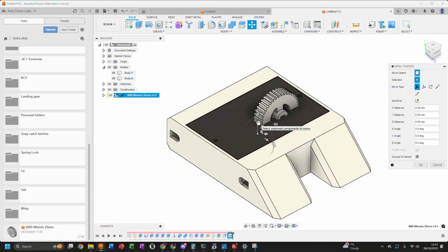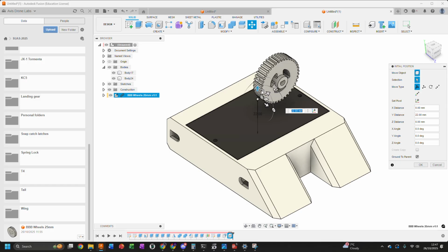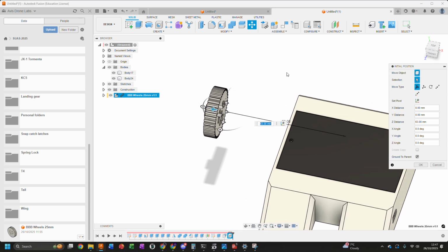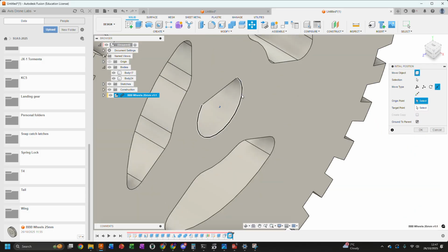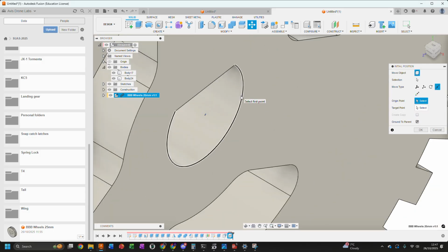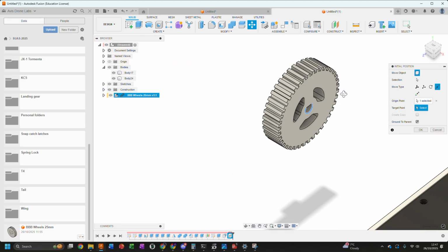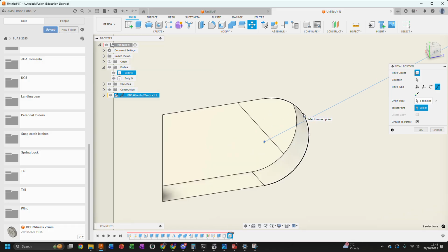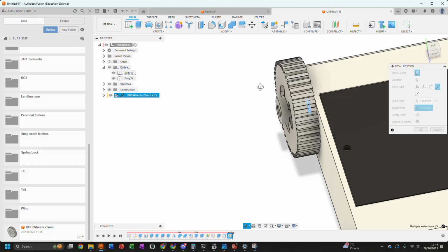So yeah, it never ends up in a useful position whatsoever, so what we're going to do is just drag these and just position it out of the way to begin with. Now we're going to do a point-to-point operation. So we're going to select point-to-point here. We're going to select this partial circle here, and we're going to see that the blue little cross in the middle is selected. And then we're going to go over here, going to make sure that that similar blue cross is selected. And we're going to do that. Just click it, and there we go.